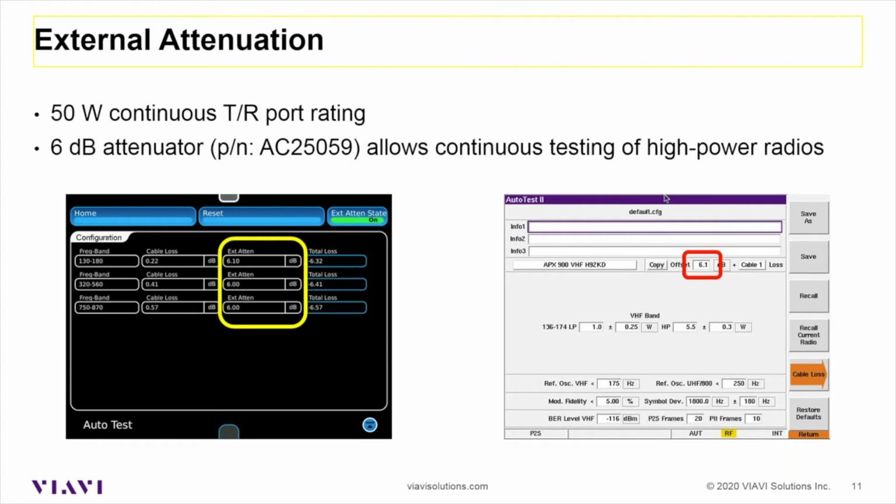Now, I do have customers that will go ahead and sweep the attenuator and the cable at the same time. And if you always have that attenuator hooked up to that cable, that's fine. That's a neat way to do it because you don't have to manually put in a number, but it does give you the option of doing so when you need to.